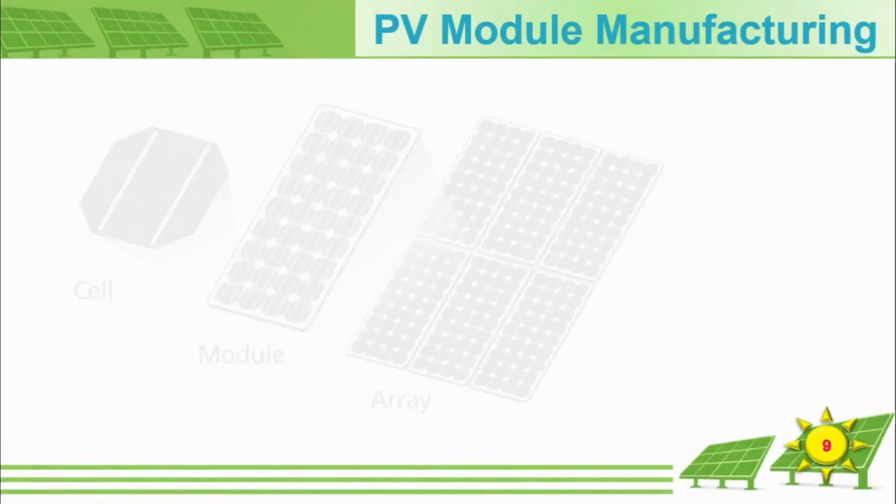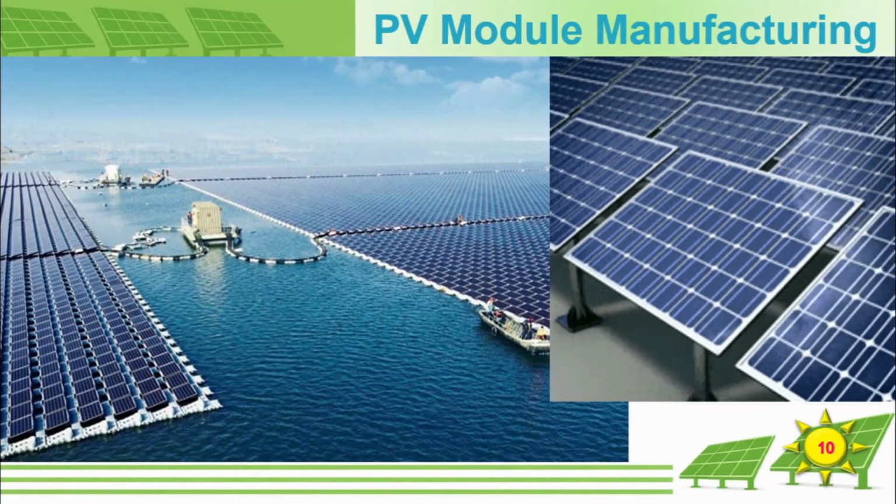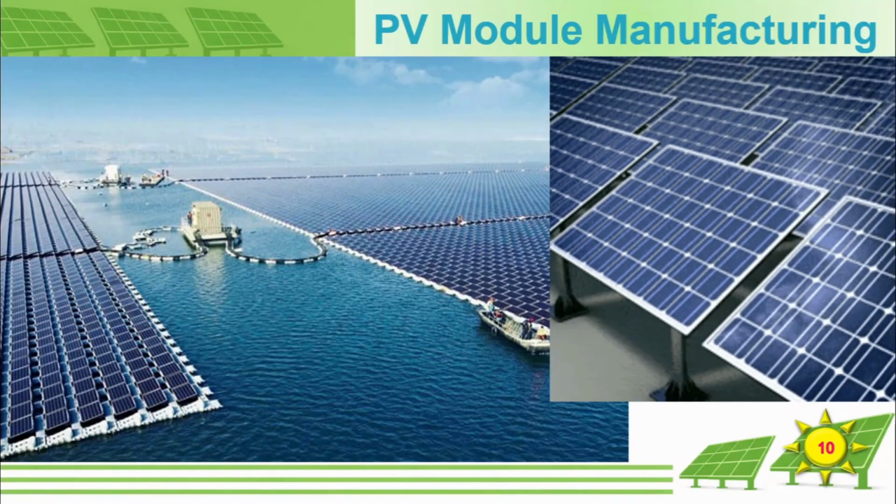This was an introduction to the different layers of a solar panel, which I hope has been useful for you. Keep in mind that the solar cell is the smallest unit used to convert light into electricity. By carefully placing individual solar cells next to each other in a series connection, a complete solar module is formed. And by placing modules together and connecting them, arrays are created for large and small solar energy projects. Up to this point, you should have become generally familiar with how panels are made and their internal structure.